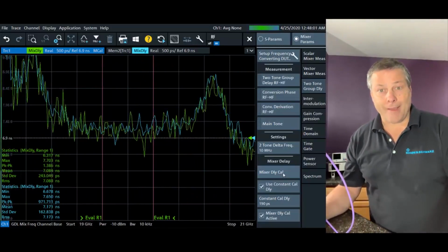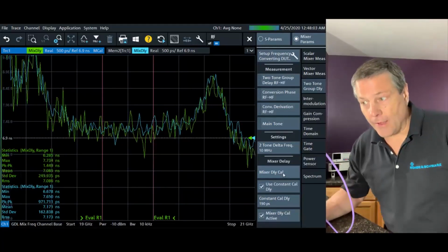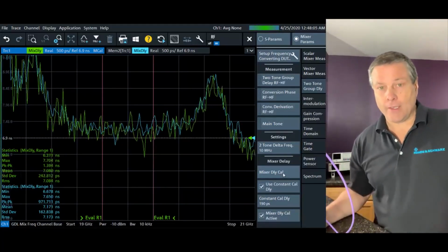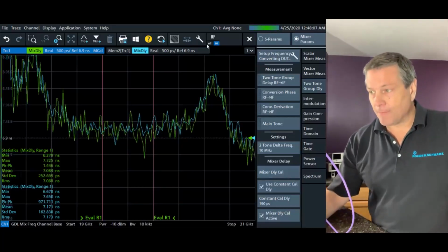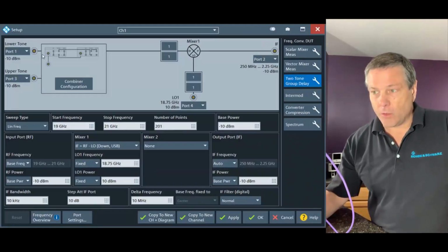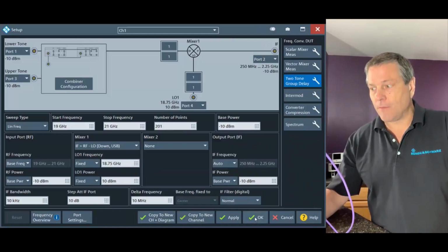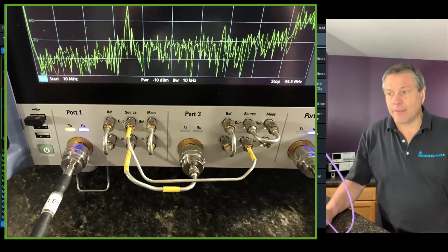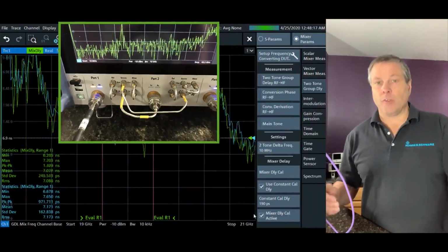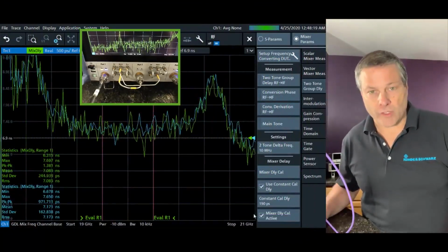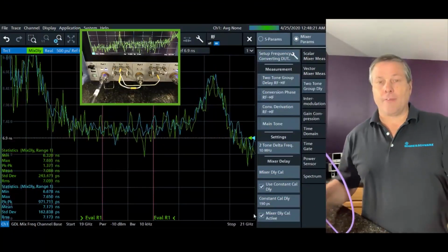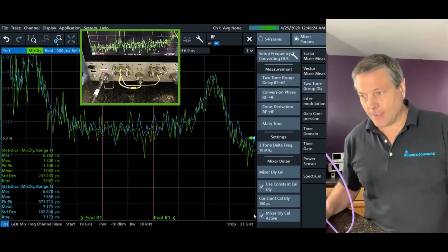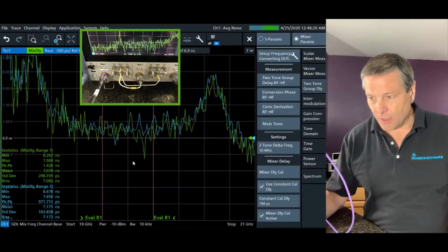Okay, I'm back. Again, quicker than I thought. So now I'm looking at the third technique, which is using the coupler as a combiner. Let's take a quick look here. This configuration looks like this. In this technique, I'm creating the two-tone signal using the port 3 coupler, which was otherwise sitting idle. I've calibrated and then connected the device under test. So this is what the measurement results look like.